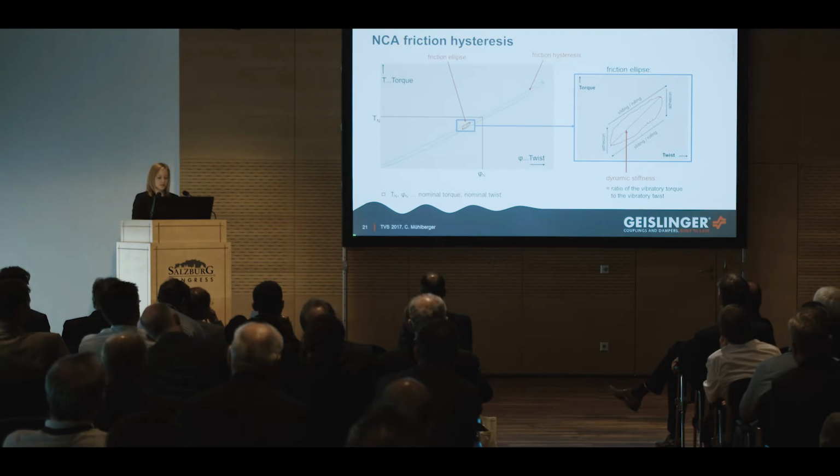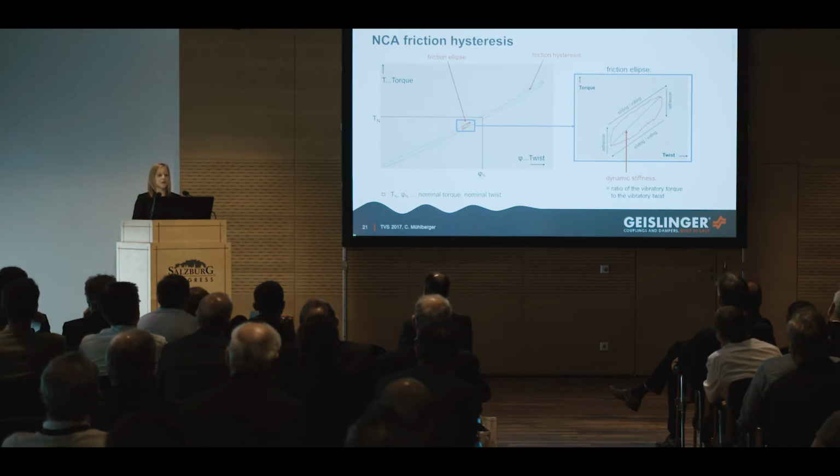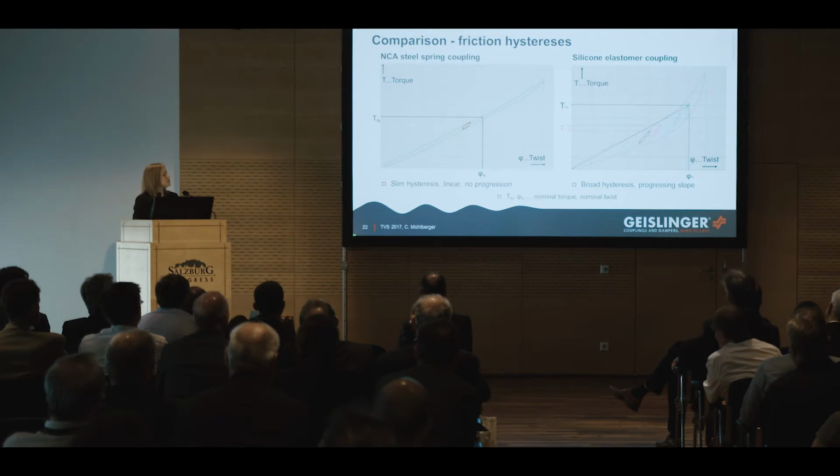This slim hysteresis indicates that for smaller twist amplitudes, the dynamic stiffness is not increasing as much as it would for another coupling. And this linearity also indicates that an increased static preload on the coupling would not affect the dynamic stiffness.